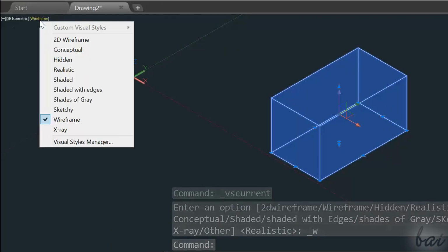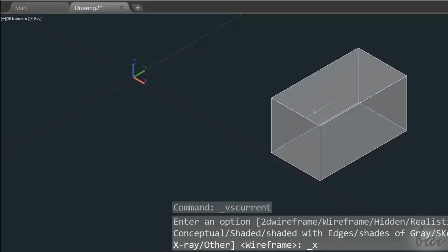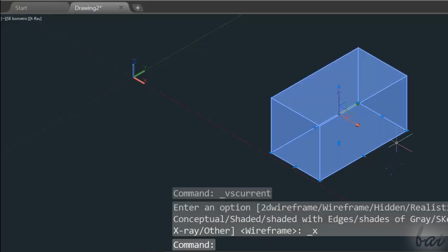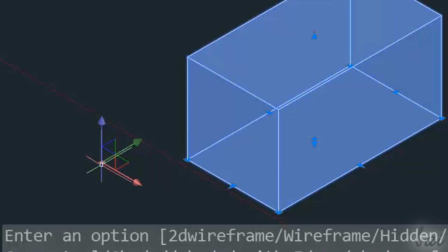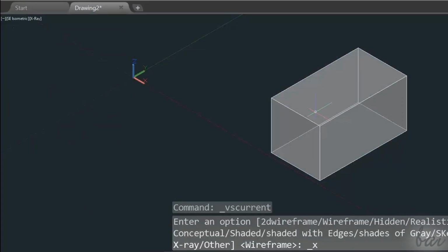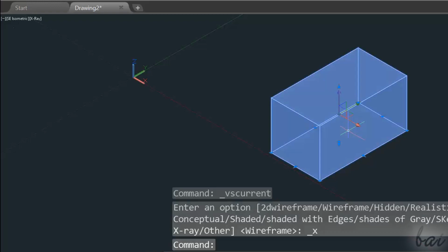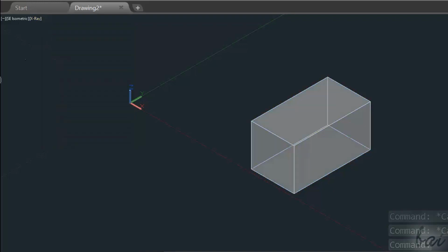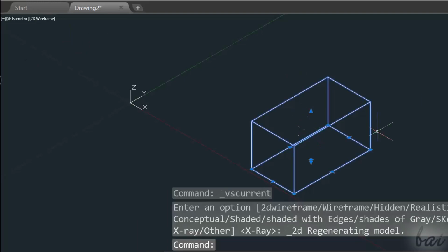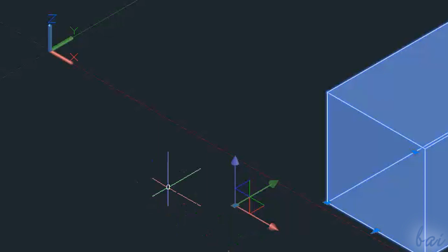While you edit, it is better to use an X-ray view that shows objects with some transparency to make you see all the nodes available. You can also use the 3D gizmo, which is the Cartesian system that appears close to your object when you select it. First of all, this system appears only in 3D views, so in all views except the 2D wireframe in the list. Then, its axes are the same ones of the main Cartesian system, indicating the same directions.